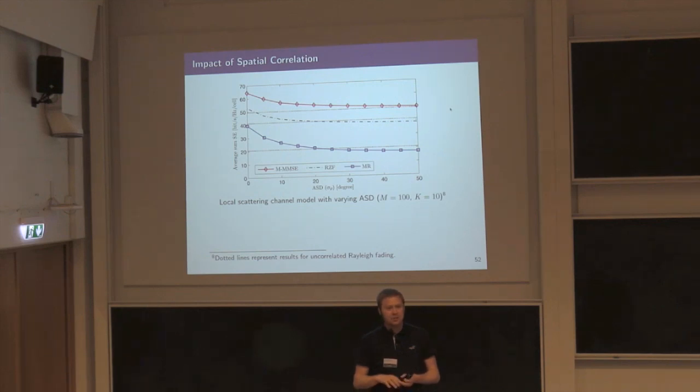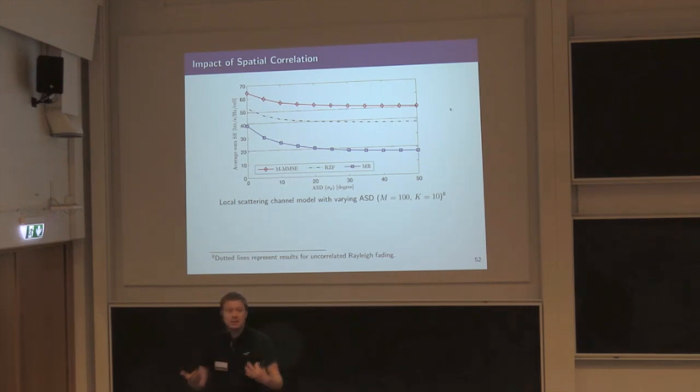But it might be that you can find a location, I'm here, my users are at these particular locations, in which case I will be better off with uncorrelated fading than with correlated fading. But if you are looking at many different snapshots, on the average, or in terms of a CDF curve as you move around in the world, you will be better off with correlation.